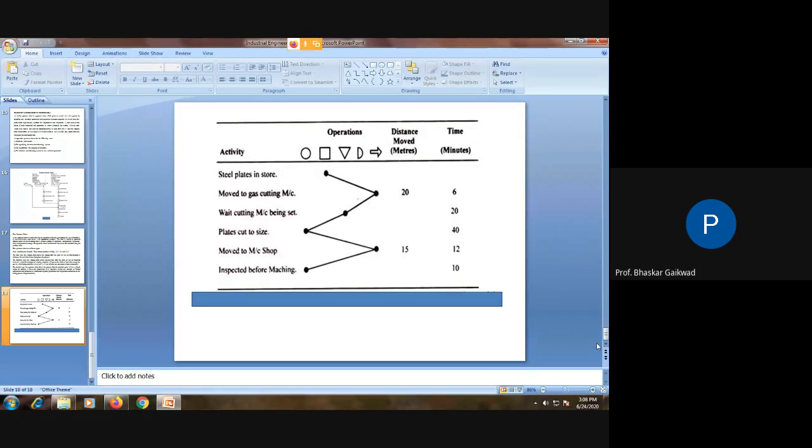To combine them, we have to manufacture such a type of die, that is called a compound die. Means within one stroke of the machine, you will get completely finished washers. So here one operation we can reduce, and inspection. Previously we required two times inspection, while manufacturing the ID and while manufacturing the OD. But if you use the compound die, both operations can be done simultaneously, and the inspection of both operations can be done at a time. So one inspection we can reduce, and one operation we can reduce.